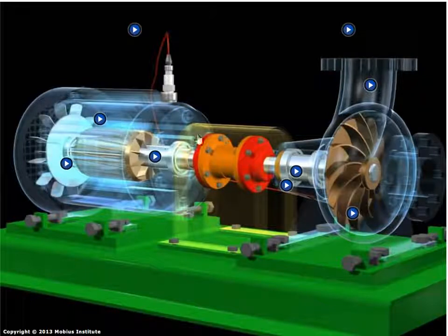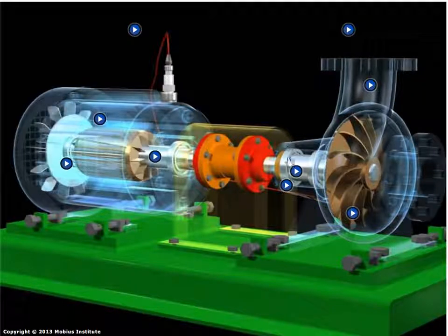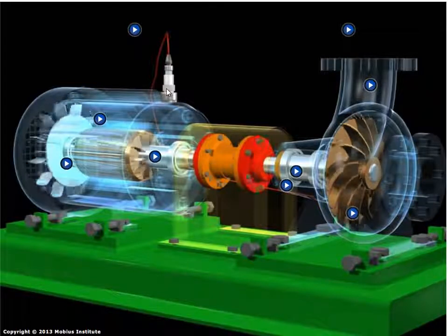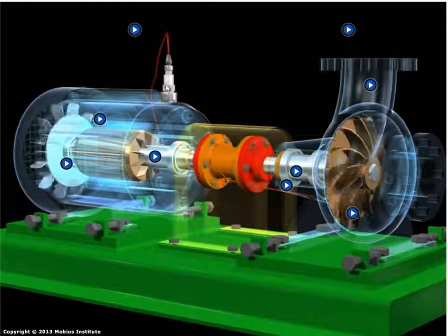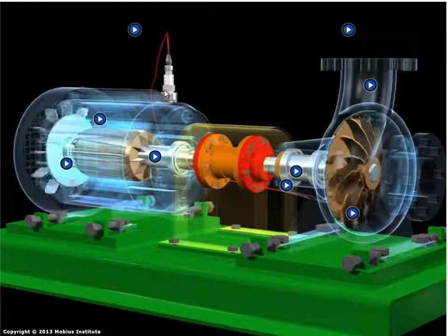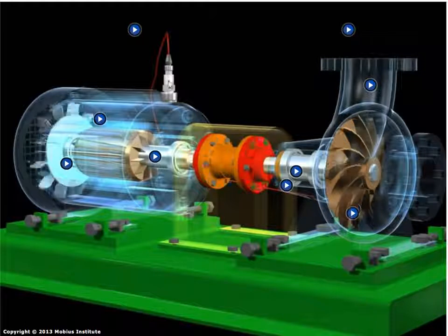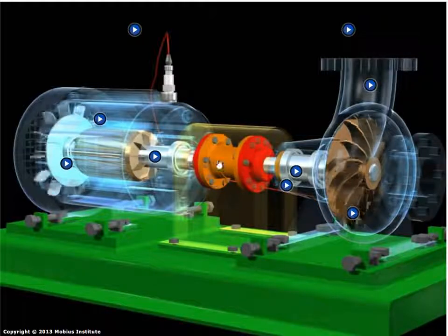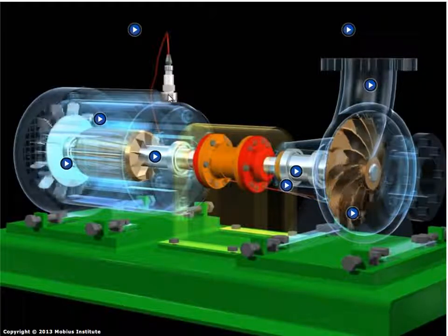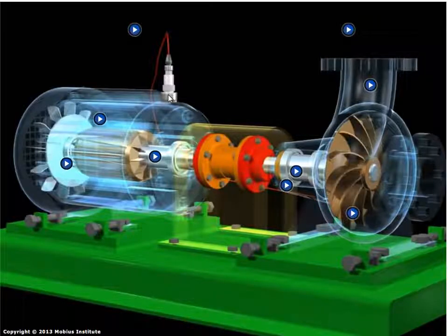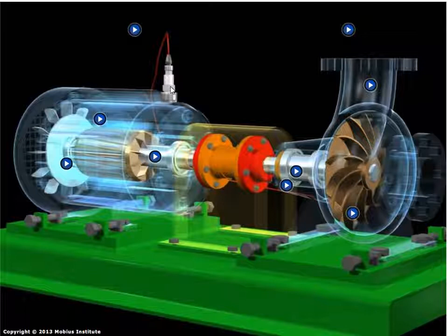Now, in this case, we've got the motor driving a pump and a vibration sensor sitting up on top. Now, I'll explain a bit more about that in just a moment. But you may first imagine that all the vibration is transmitted along and goes up to this point, and maybe from this side as well. And that's one of the things I'll mention a bit more about in a moment. Just where is the vibration coming from, and how's it getting to that sensor?